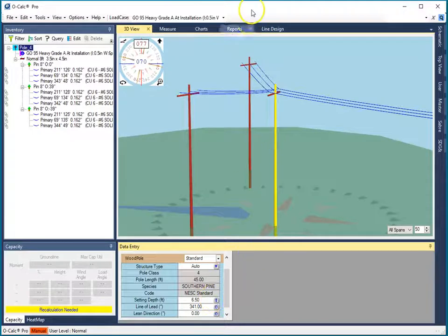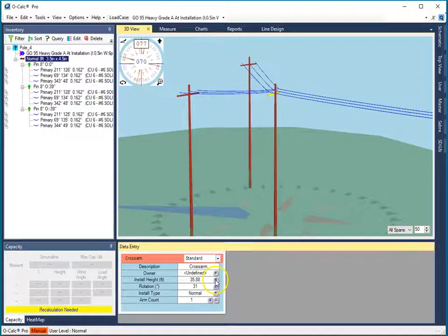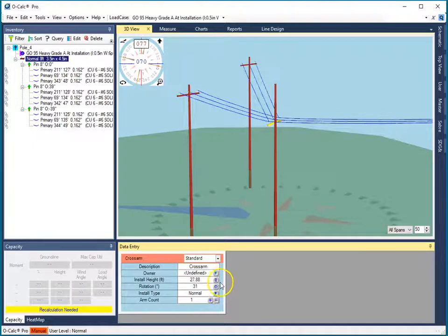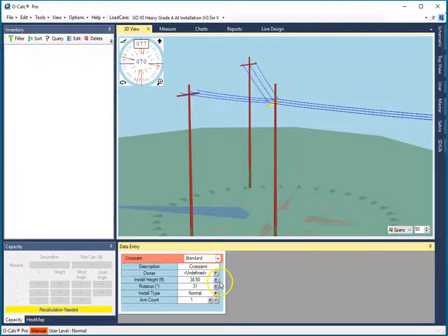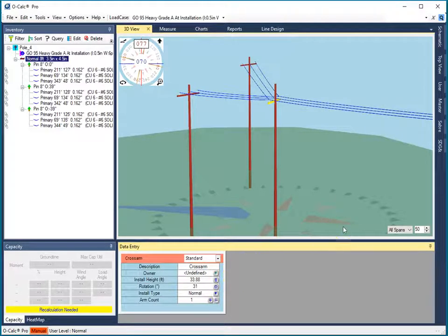They rotate, even though under the covers, this is a pole with 3 spans on it, this is a pole with these 3 spans on it. If I were to separate these PPLX files and deliver them individually, they would keep these geometries. But while they're connected together in the line design mode, they maintain the proper relative geometry so that the endpoints stay the same. And that's true even if I grab this cross arm and lower it down. You notice that the end drop rise heights on the spans on either end totally understand that I'm performing that operation, and they adjust accordingly.